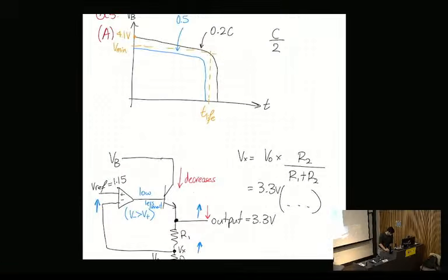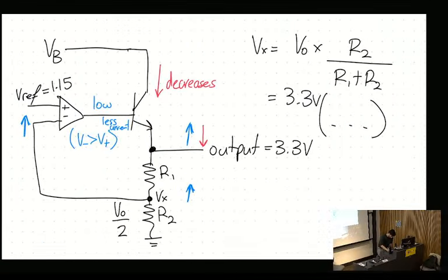Cool. So we're going to need this context as well, because the dropout voltage is referring to the dropout voltage across this transistor. So fundamentally, how the LDO reduces the amount of power is it dissipates it through that BJT, and that also sets a limit, because we need to keep the BJT on. And the BJT is only on if we supply enough voltage. I think in this case it's 0.4 volts. So VB minus the output must be greater than the dropout voltage, otherwise the LDO stops working because the BJT isn't on anymore. Okay? Question?